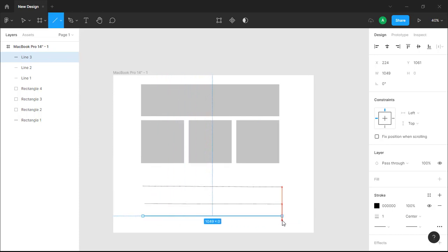But if you're trying to drag it without the Shift, I think that depends on your accuracy or how long you've been using the mouse. But to get a perfectly straight line, you just try to drag this. You see at this point now, my line is going at, let's say, angle 45, but the moment I hold Shift on my keyboard, you see I'm getting a perfectly straight line. So I'll stop there for the line tool.